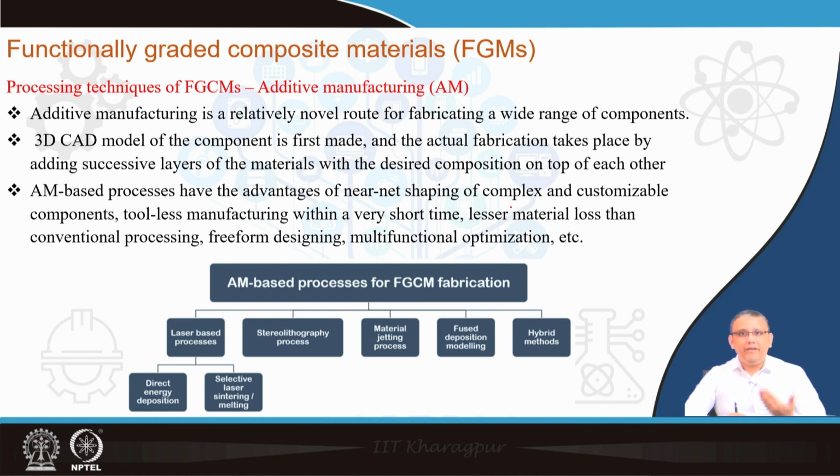It is a mold free process, it is free-form design, because you do not need any mold for this process. We also have a very small amount of material rejection, and AM can fabricate the component in a very short time. There are also many variants of the AM process. Initially it was only designed for polymer or metallic components, but nowadays even ceramic matrix composites can be fabricated using AM techniques.